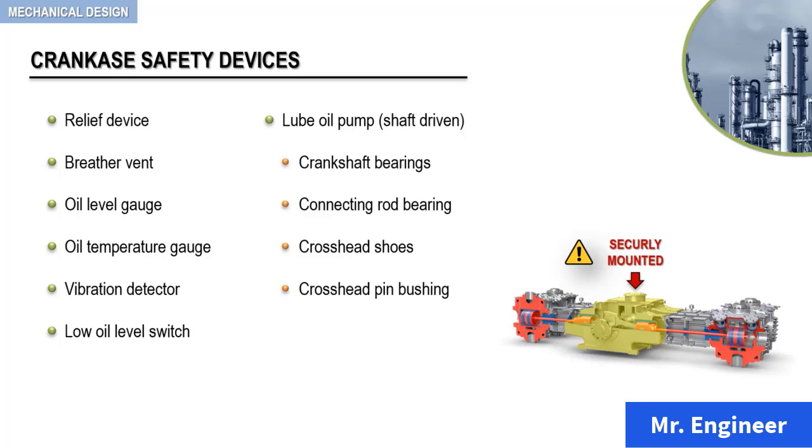Epoxy grouts provide high bond strength and are oil resistant. All reciprocating base plates should be checked on a continuous basis for any evidence of foundation cracks or discontinuities, and should be repaired at the first opportunity.